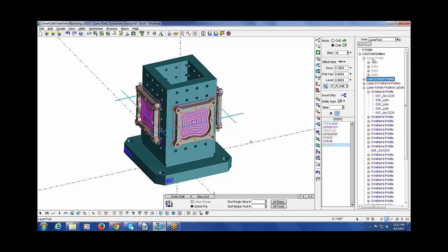I got a quick question, Doug. This is Mike again. When you did the drilled holes in your example, when you had them at different levels, that's how it sorted them. Let's say if you're using a spot drill, you might have that at different levels, but only want it to be one sequence of events. How do you deal with that?